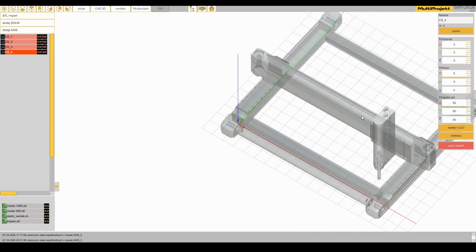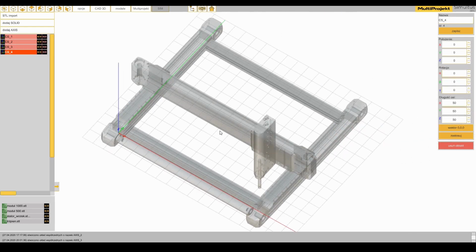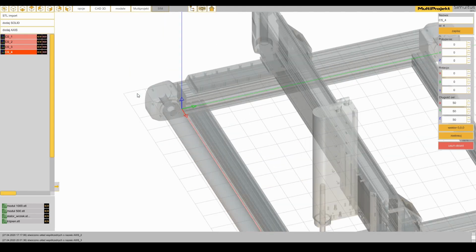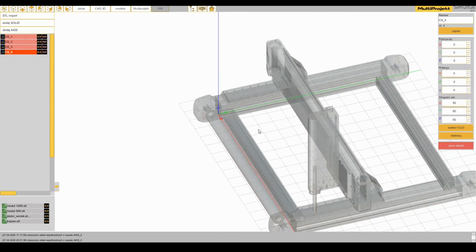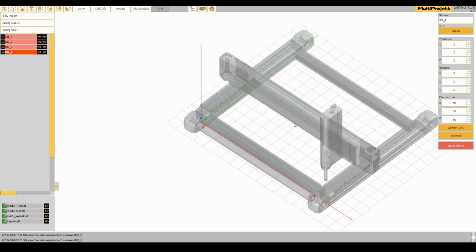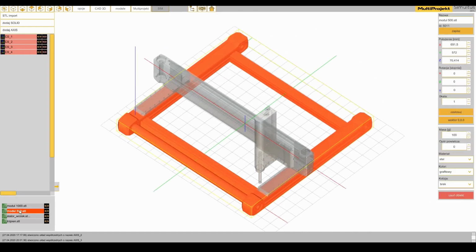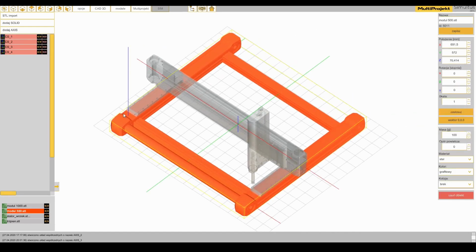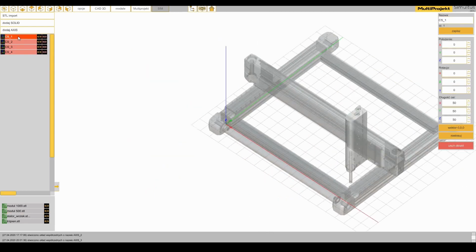We will now introduce kinematic relationships resulting from the design of our device. Let's take a closer look at its kinematic chain for this purpose. Its base is the fixed base of a double module with a stroke of 500 mm. The blocks of this module will move along the green y-axis. So let's add the letter y to the name of the first coordinate system.